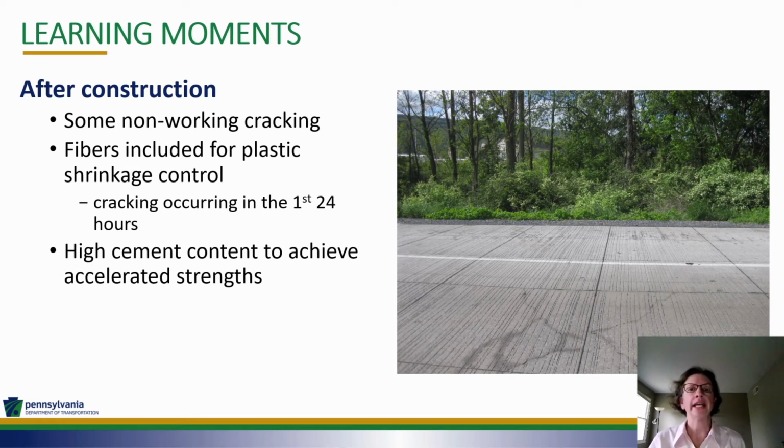Some non-working cracking was observed, that is, fine cracking that does not appear to be moving. Fibers had been included to address plastic shrinkage cracking. However, when reviewing the concrete mix design, it was discovered that a very high cement content was used to achieve the accelerated strengths required by the specification.